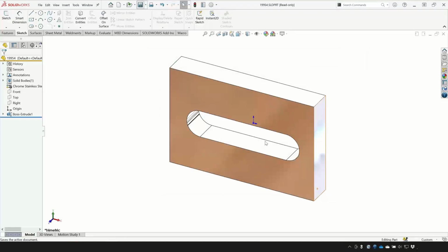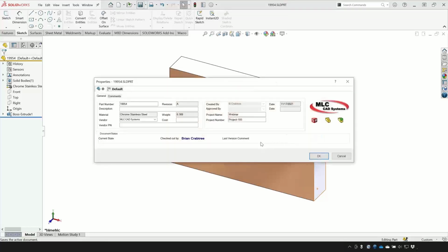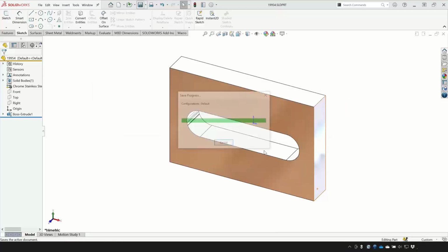But if you are using PDM Standard, that's not a problem. You just input the number that you know right there, and then you'll go ahead and input that same number on the part number here. We'll give it, let's say, spacer block. And you'll notice that I only had to update the description. Everything else was automated for me. I could also put in other vendor information and cost information if I need to, and go ahead and save that into the Vault. Now, that's very, very simple, right?